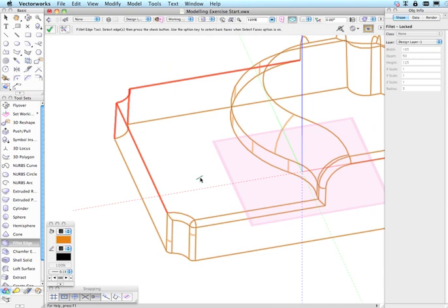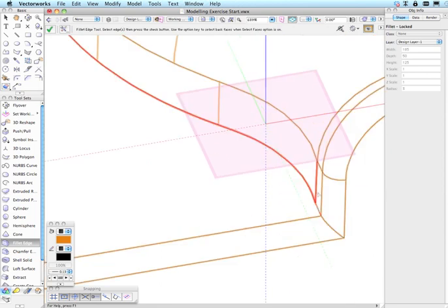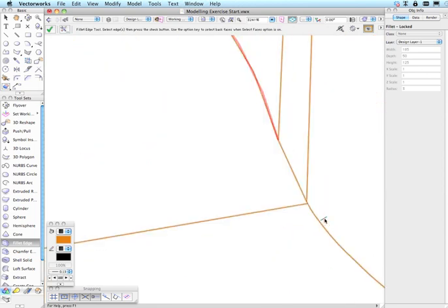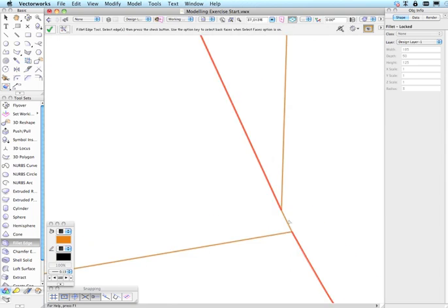Oh, I made that. We've already got a fillet there, and this edge here. Now it gets a bit tricky right down in this corner here, so let's zoom in and take a closer look. I'll select this edge here, and I also want that corner there, and you'll notice there's a tiny little piece in here, and we have to make sure that we get that.